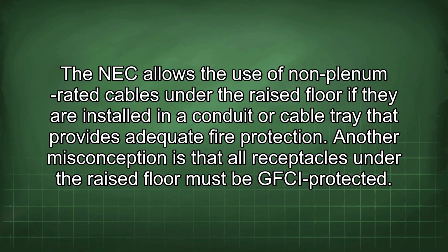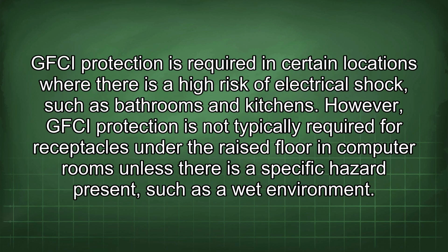Another misconception is that all receptacles under the raised floor must be GFCI protected. GFCI protection is required in certain locations where there is a high risk of electrical shock, such as bathrooms and kitchens. However, GFCI protection is not typically required for receptacles under the raised floor in computer rooms unless there is a specific hazard present, such as a wet environment.